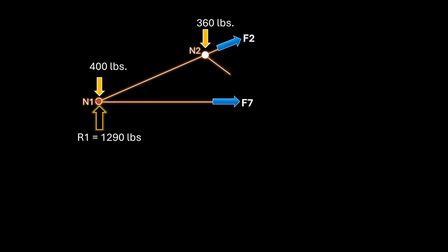We have calculated the forces at member 1 and member 7. The next member that we will evaluate is member 8. Actually, we do not even need to know the forces at member 1 and member 7 in order to determine the force at member 8. We are going to use the method of sections, which is very useful when you need to quickly determine the internal force of a particular truss member.